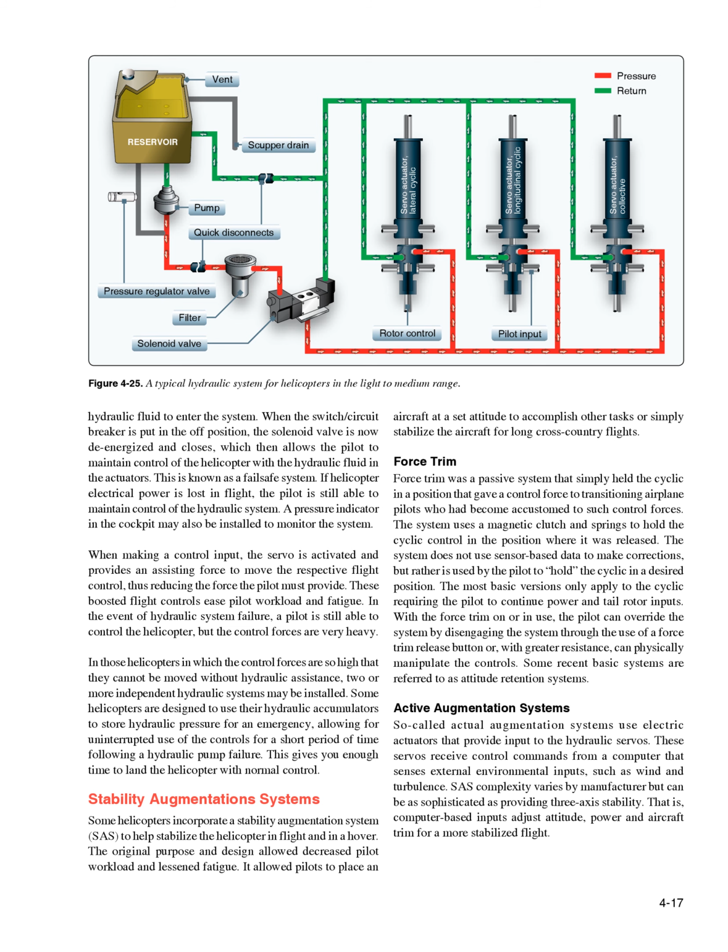Some helicopters are designed to use their hydraulic accumulators to store hydraulic pressure for an emergency, allowing for uninterrupted use of the controls for a short period of time following a hydraulic pump failure. This gives you enough time to land the helicopter with normal control.